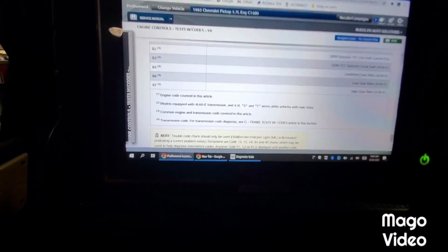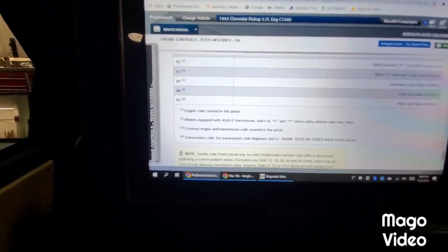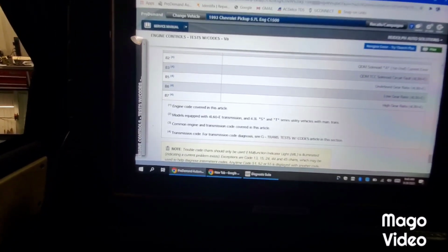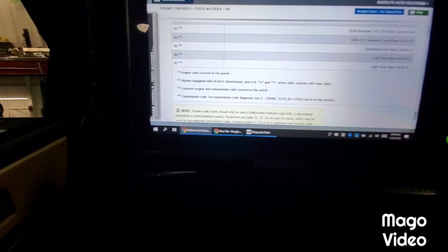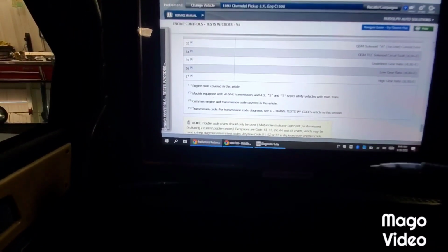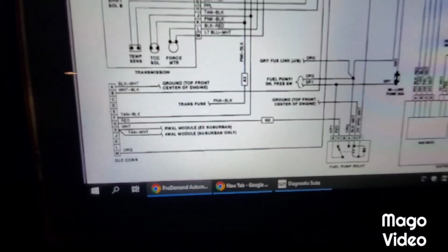So we want to go after this fuel pump. Now remember I said it kind of has an extended crank. So are we dealing with a bad pump? Are we dealing with a bad fuel pump relay? I mean, that's where I'm headed. I guess I could get some more information. The customer wasn't complaining about long crank time, wasn't complaining about any drivability issues, but that's the reason, code 54. So let me do some research on this circuit.